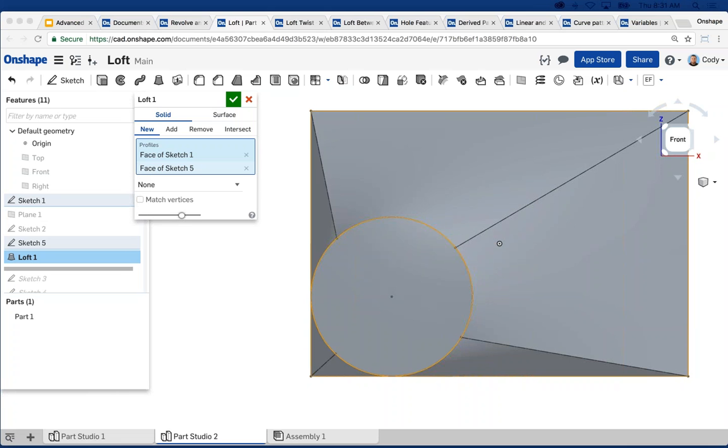But again, in your example, I'm sure you can split it any way you'd want using any combination of degree dimensions that you want. All right, so I've split the circle, and as you can see, when I loft between a split circle, it lofts between the vertices that are created when I split it. So that's one of my first tips. In general, with the loft command, have the same number of vertices on each profile. It will help to align the transition between shapes, right?